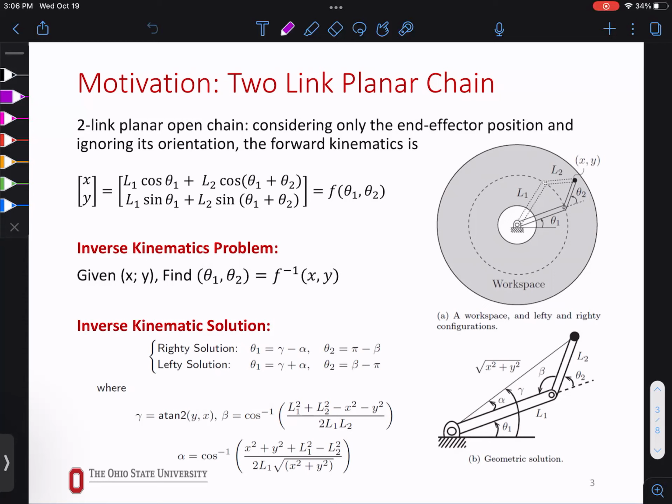You see that the end effector is the gripper, right? Sometimes we use a gripper. The only thing it does is grip and secure and then come back. That's why we don't care right now about what the gripper does. We just want to know where the wrist will end, because from there it's just an action that happens. There are a couple of other things that will be involved, like force control, to make sure the cup doesn't slide through. That's a different kind of control. So in our inverse kinematic, we also care where the joints need to go.